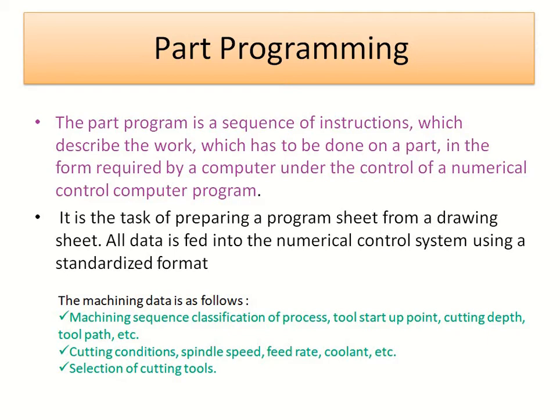The machining data is as follows: the machining sequence, classification of processes, tool startup point, cutting depth and tool path. Second, the cutting conditions: spindle speed, feed rate, and coolant on/off can be specified. And finally, the selection of the cutting tools.